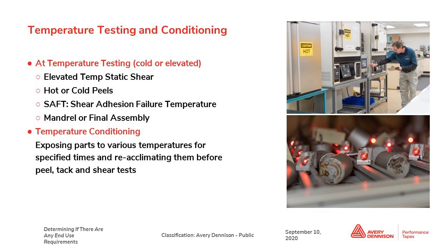We can also do peel adhesion testing at elevated or cold temperatures. We have hot boxes where we can put our Instron machine arms in an elevated hot box to peel at elevated temperatures. Avery Dennison also has giant cold rooms where we can bring the temperature down. It's very much like a meat freezer for restaurants that you can go inside and run the peel adhesion or other types of tests at the lower temperature.